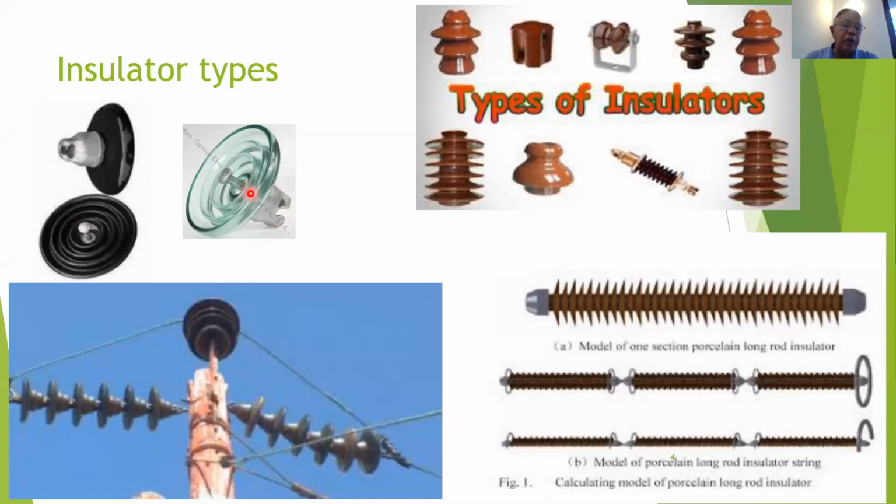So on the bottom, you can see an insulated string combined with cap and pin insulator construction, a 66 kV line. And on the top, your jumper goes on a pin insulator. Now, here you can see the pin insulators, a pin insulator here, and another variety of pin insulator with higher creepage.